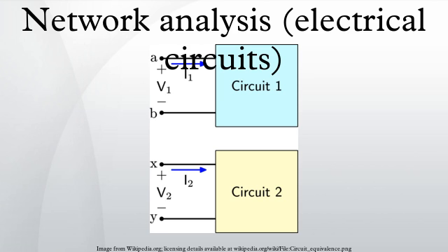The diode equation above is an example of an element constitutive equation of the general form. This can be thought of as a nonlinear resistor. The corresponding constitutive equations for nonlinear inductors and capacitors are, respectively, where f is any arbitrary function, φ is the stored magnetic flux and q is the stored charge.